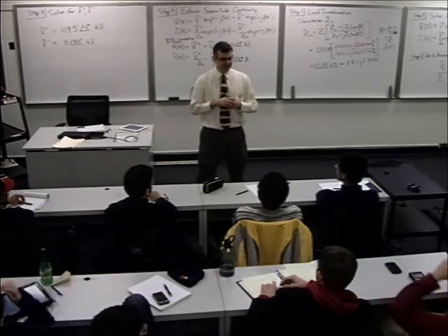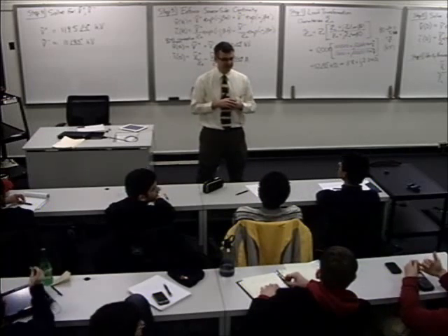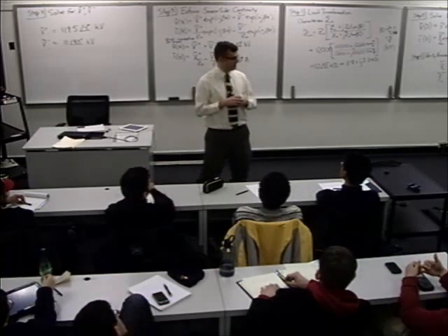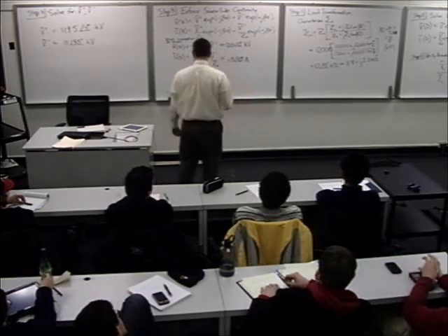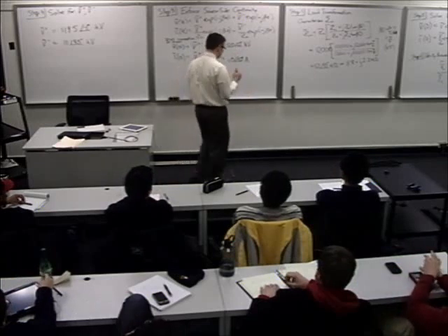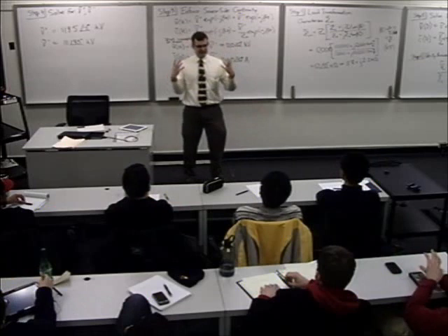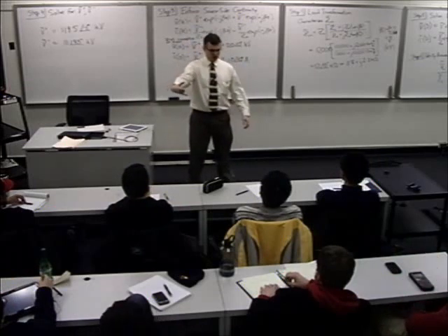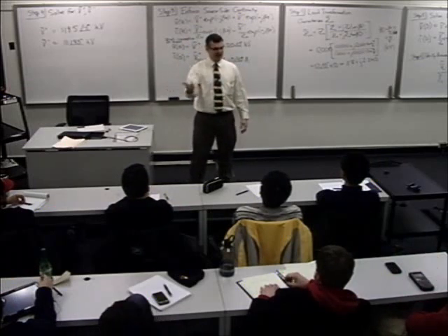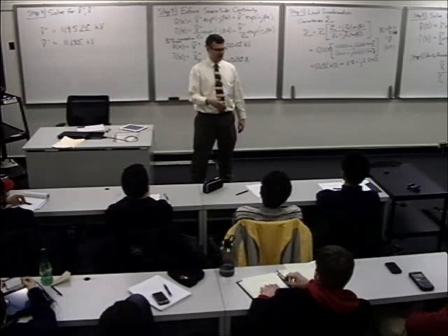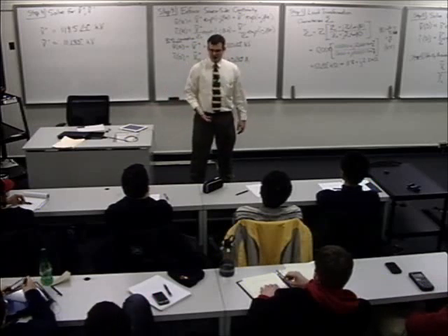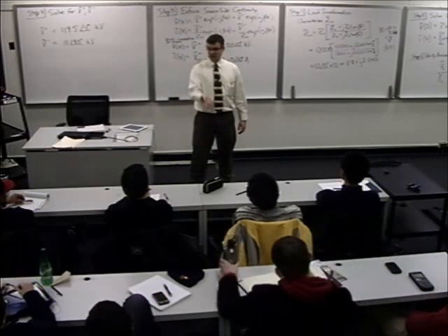Is the power going into the line going to be the same as the power going out of the line? Yes, that's a great question. In this simplified system I only had one source putting out power, so you can calculate that very easily. It's the real value of 1/2 the complex output voltage times the complex output current.